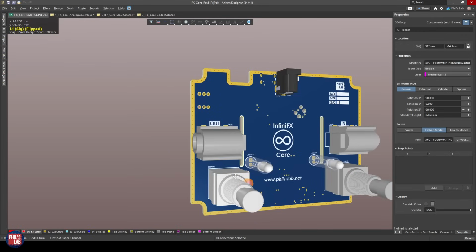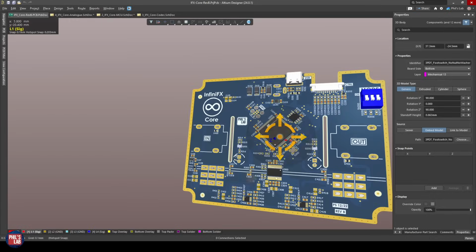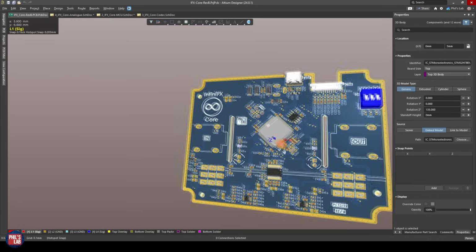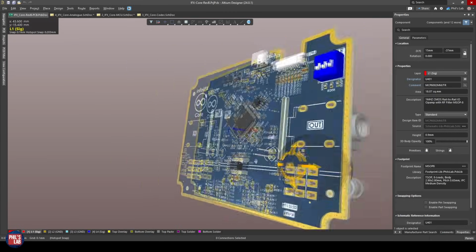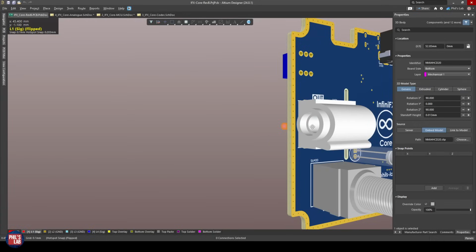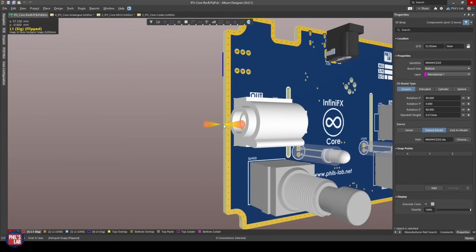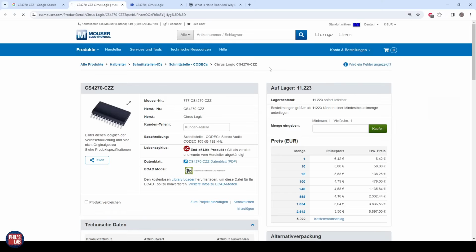Then we toggle this foot switch and we don't get a true bypass. That is, our in jack is routed through the analog front ends, goes through the codec into the STM32H7 microcontroller. We do a tiny bit of conversion, send the data out again to the codec through the front end and to the output jack. So we measure once as a baseline, so to speak, and then once with our I2S feed-through system engaged to see what our absolute minimum noise floor performance is. This is, of course, limited by the analog front end. That will add some noise.